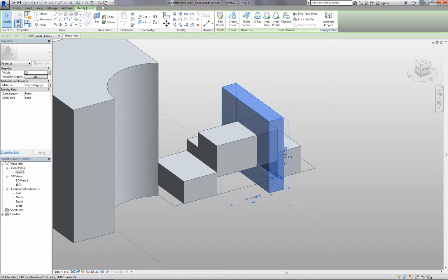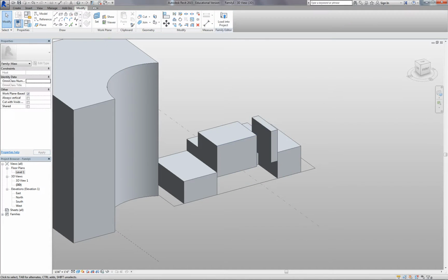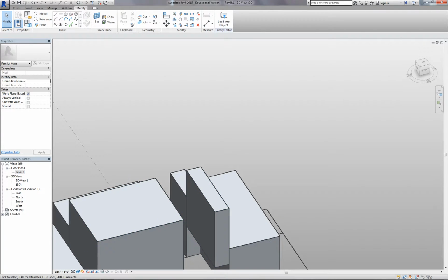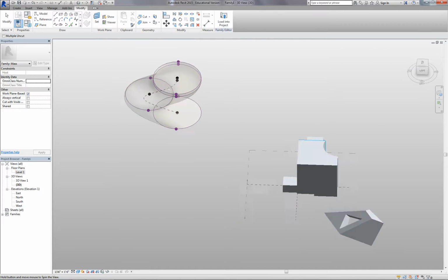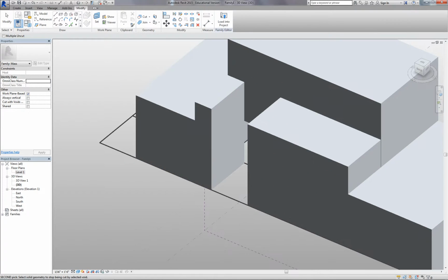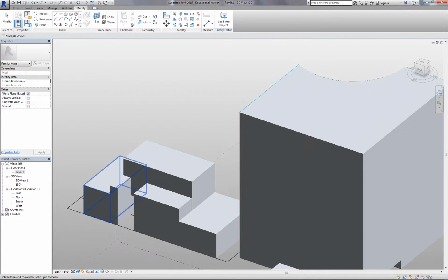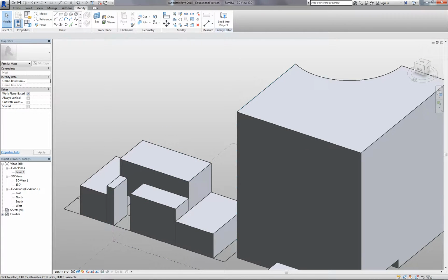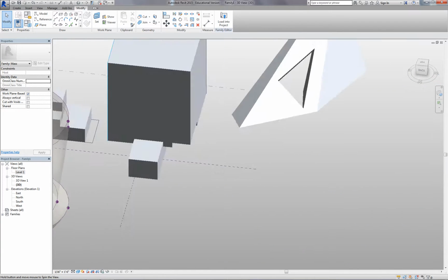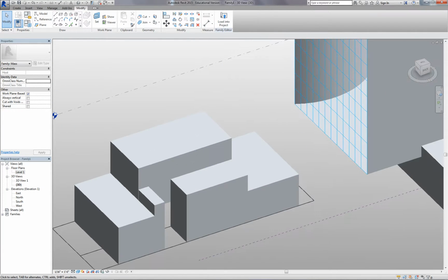So if I go ahead and convert this to a void, we maybe don't want to cut this shape, so we can do an uncut, and put it back, only cutting one of the geometries. So uncut will be a technique, because typically it cuts through everything, but you might want to uncut it. I know I'm throwing a lot at you guys right now, but it's pretty straightforward, somewhat.